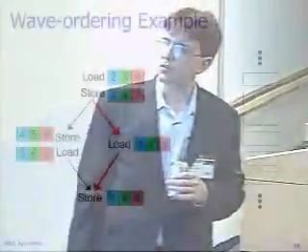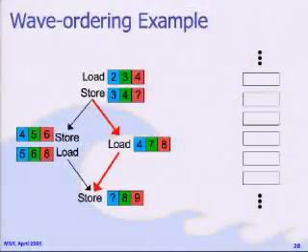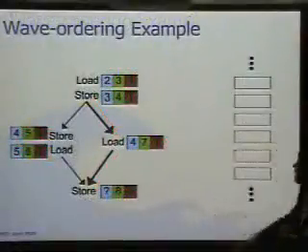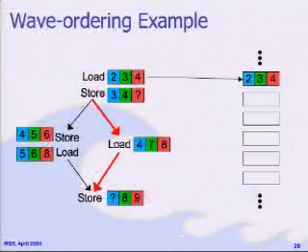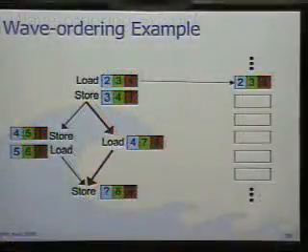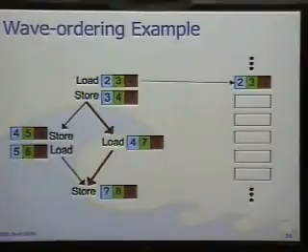So I'll give you an example of how this works in practice. So we'll assume the control is going to take the right-hand path. And remember, things can execute in any order. But to keep things simple at the beginning, we'll say that the top load fires first. And it tells the memory system, I'm operation number 3, and the next memory operation you should expect to see is operation number 4. If operation number 4 fires next, it'll tell the memory system, I'm operation number 4, but I don't know what's coming next because I'm at a branch point.